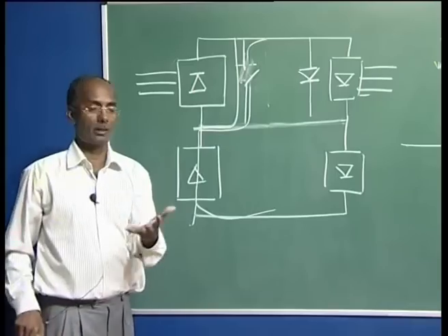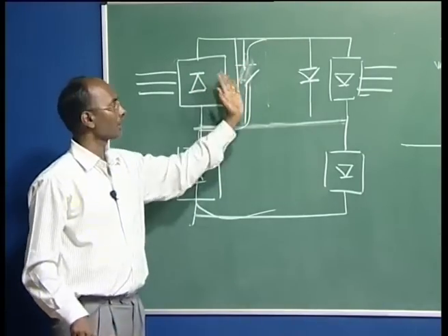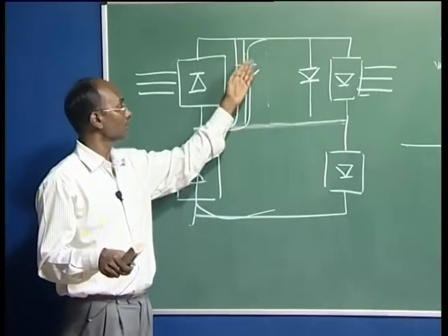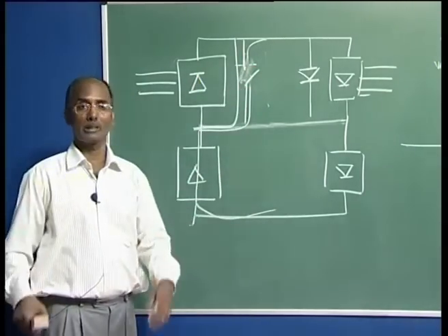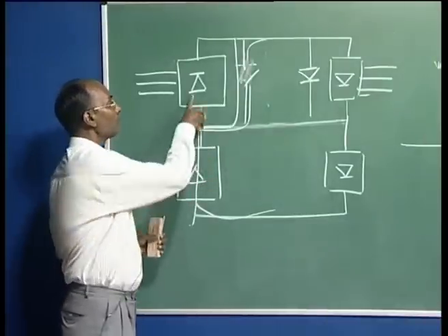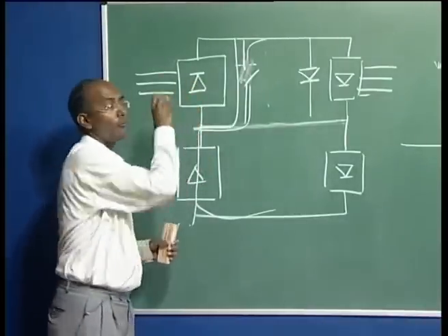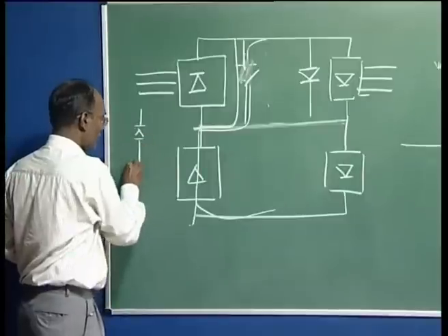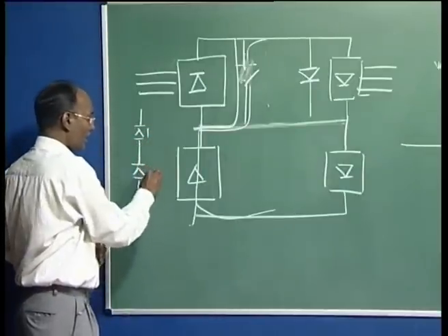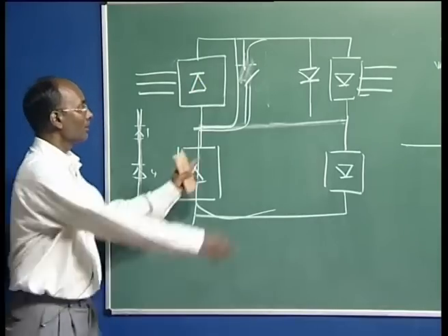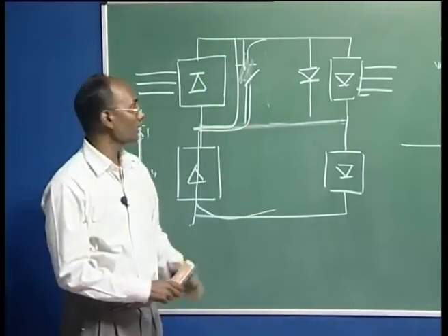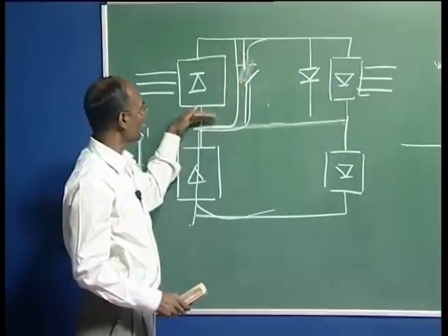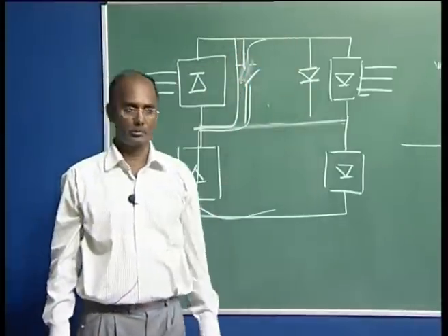It is just like a circuit breaker. If voltage is there between these two connecting points, there will be a huge spark, because of the potential gradient, the air will be ionized, and it will damage the switch. So, in that case we use one pair of valves as the bypass valves, this is 1 and this is 4. If both are conducting, the voltage across this becomes 0. Once this is there and the current is flowing, at that time you can close the switch and then open here, and the current will keep flowing without any problem.